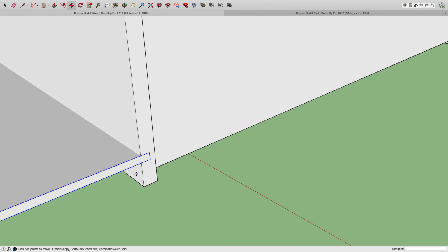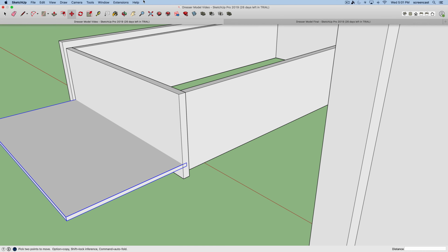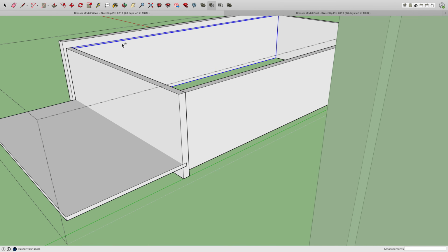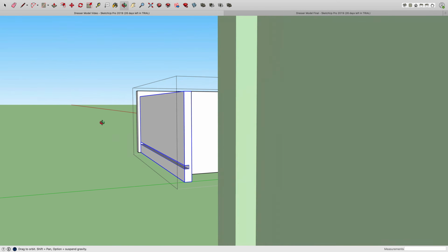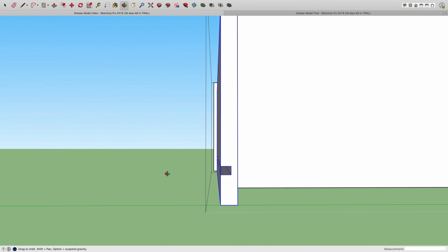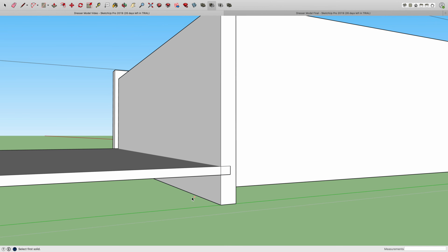So what you can do is if you have 2 pieces that overlap, you could create a big piece and put it in the middle and then do this method. So you can come into your solid tools. I have them here on my board here, but you can get your subtraction tool. So we can subtract this one from this one, and you can see that it just cuts that out really nice. So that's a really cool way of doing a little dado, and there's nothing wrong with that. It works fine. In fact, we could use it for this method. But I'm going to show you another method.